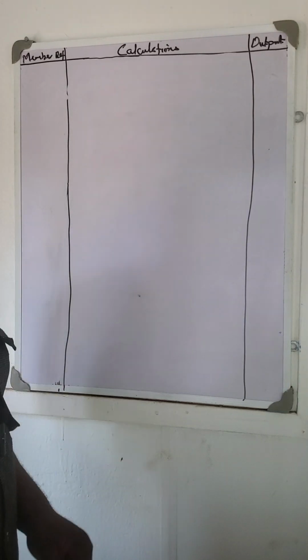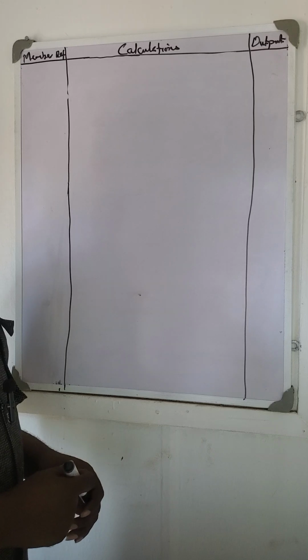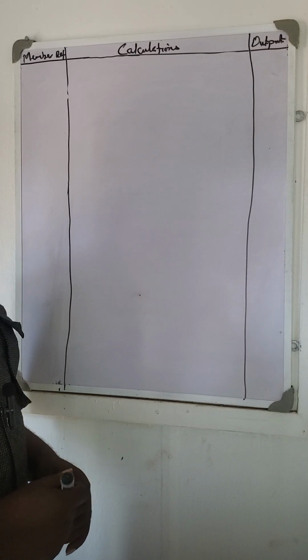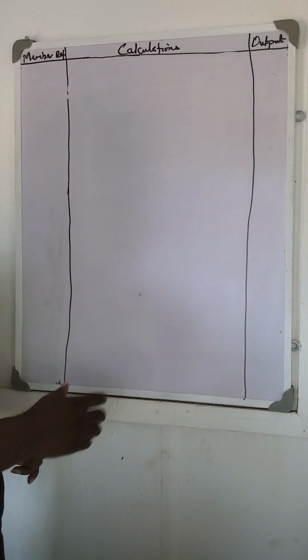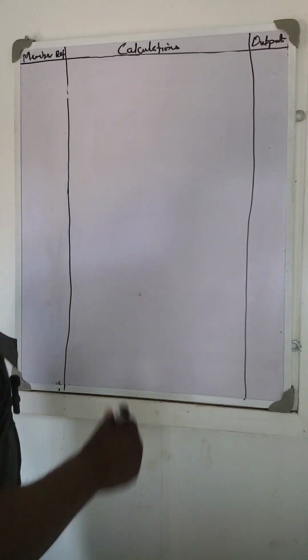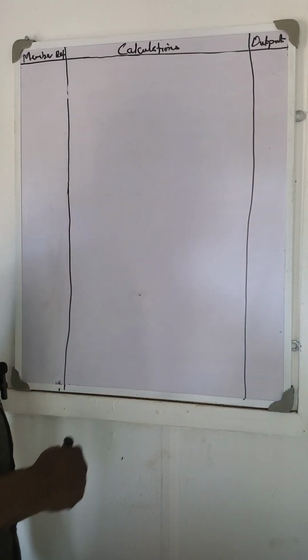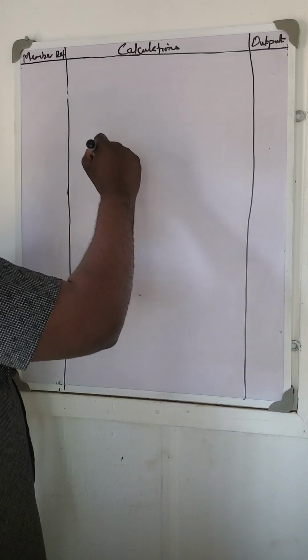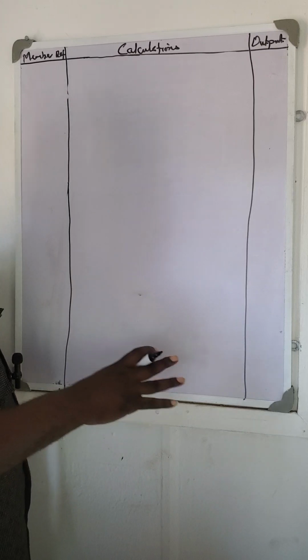We are going to continue from where we stopped. In our last class, we were able to provide for the span reinforcement. Today we are going to continue with the continuous edge. You always prepare your calculation sheet like this. Then you bring back your UDL because you are now calculating for the moment at the continuous edge of the short span.